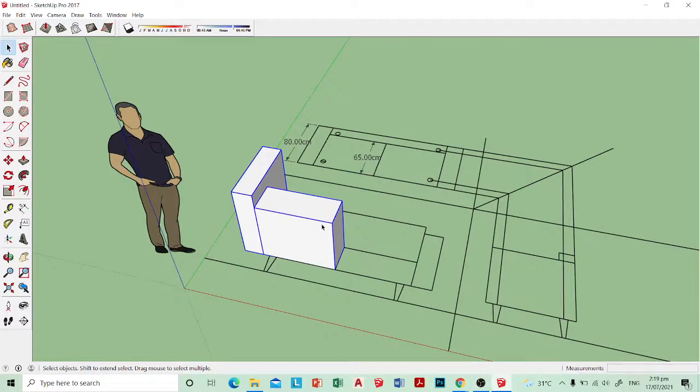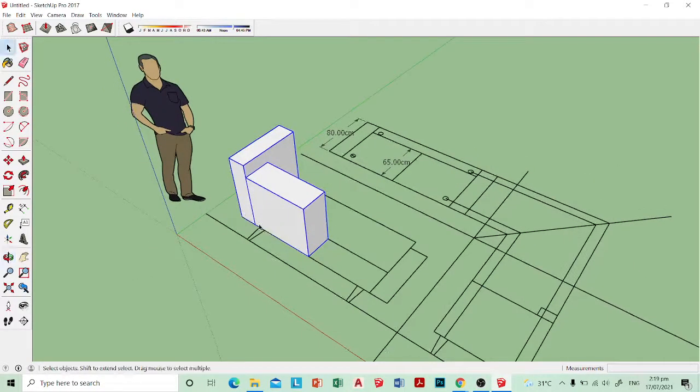I want to draw the legs now. I'll draw the legs later. So rotate. You don't even need to hold the left click for this. If you're drawing with cubes, it's a lot easier. So just put the rotate at the correct axis. I want it to rotate at the red axis, so I wait for my rotate tool to turn red, and I want to rotate it at this corner here.